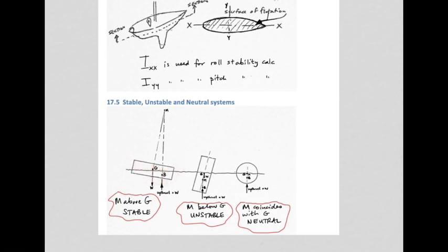Here these images have all been drawn showing some degree of displacement from the neutral position, but when M is above G, you will see that the upthrust acts through the original vertical, reaches point M up here like we discussed, and that would then cause what's known as a righting moment, an anti-clockwise moment, which would try and get the vessel back to where it belongs, back to level.